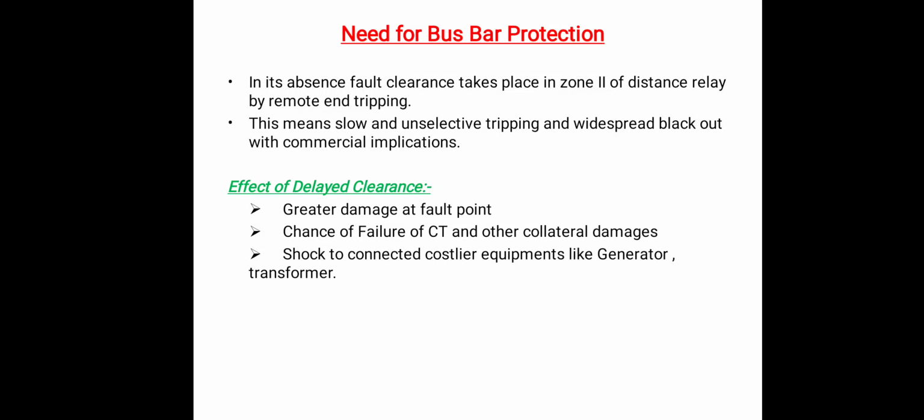This means slow and unselective tripping and widespread blackout with commercial implications. The effect of delayed clearance is greater damage at the fault point, chance of failure of current transformers and other collateral damage, and shock to connected costlier equipment like generators and transformers, as said earlier in the slides.